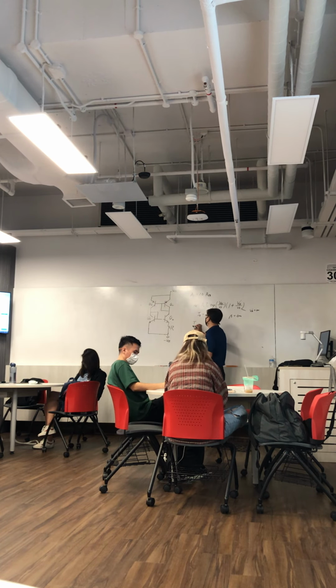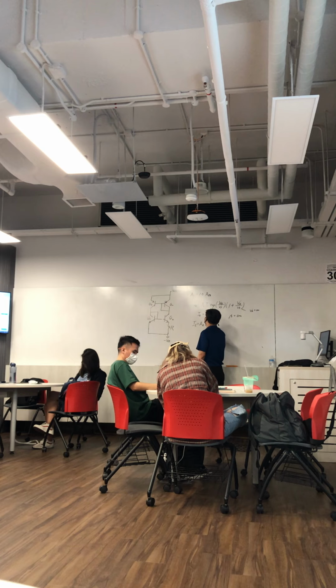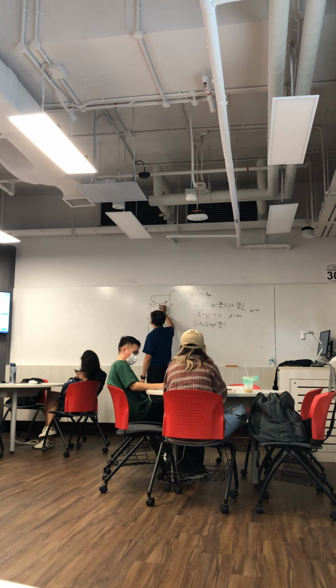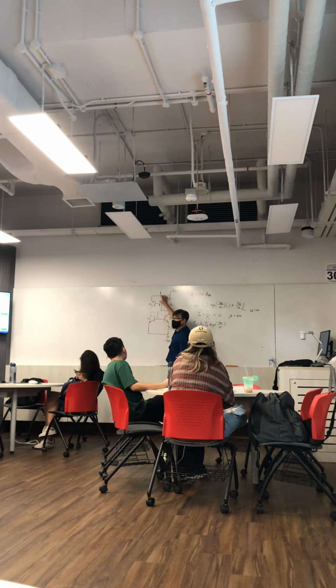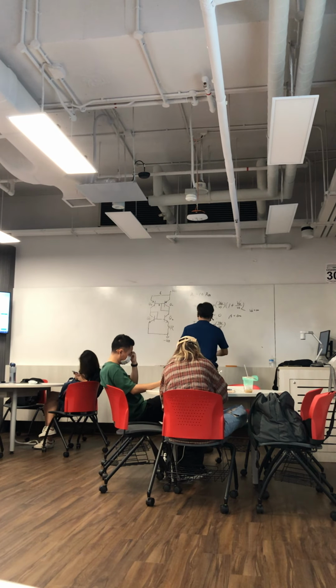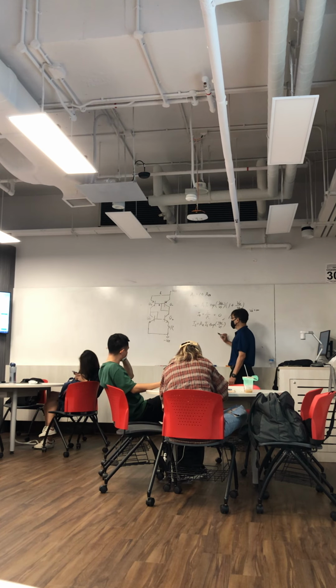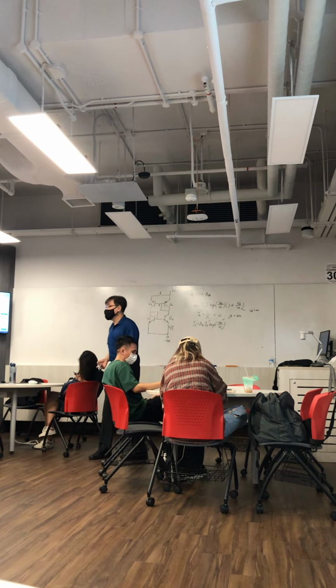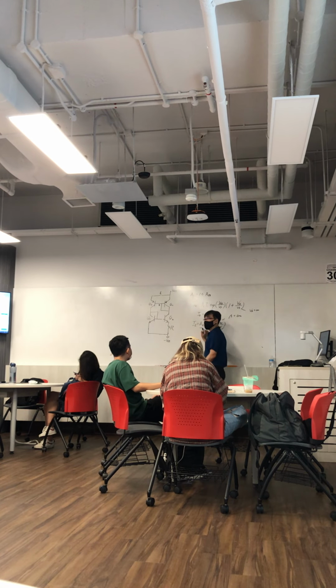So then your IC essentially is equal to IS times exponential VBE over VT because I ignore early effect based on the question. So then if that's the case, ask yourself, this guy is base, this guy is emitter, for the PNP. Do they have the same base-emitter voltage? Base connects to base, emitter connects to emitter. So if you look back to this equation, this is the same. This thermal voltage, if they are at the same temperature, is the same. IS saturation current, if they are fabricated on the same size, they are the same. So the only thing that is different is emitter area, right?